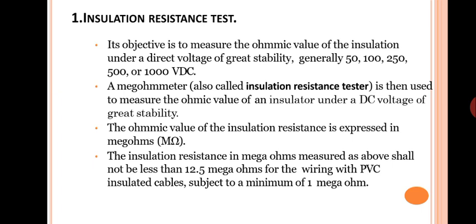the insulation. A megohm meter, also called an insulation resistance tester, is then used to measure the ohmic value of the insulator. The ohmic value of the insulation resistance is expressed in megohm.